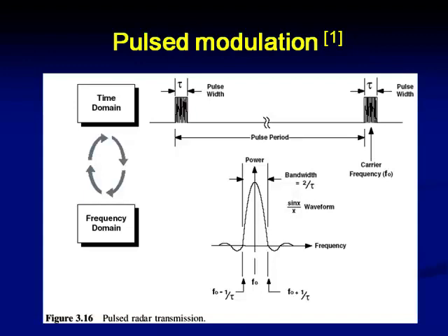If you take the Fourier transform of this, it's going to be as seen like this. So in this we have the bandwidth of the pulse required and the center frequency of this. So the pulse period, the inverse if you take, we are going to get the center frequency of this, and the pulse width will have the information regarding the bandwidth of this sinc function.